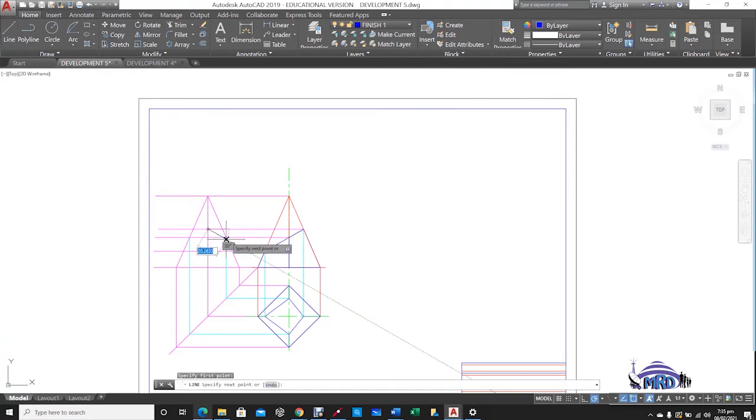A square could have been plotted here on the end view, and because it is in first angle projection, that shape would actually have formed hidden detail. But I just dropped it in there so that you could see what the shape would look like, and I'm going to take it out so that we don't further confuse the issue.